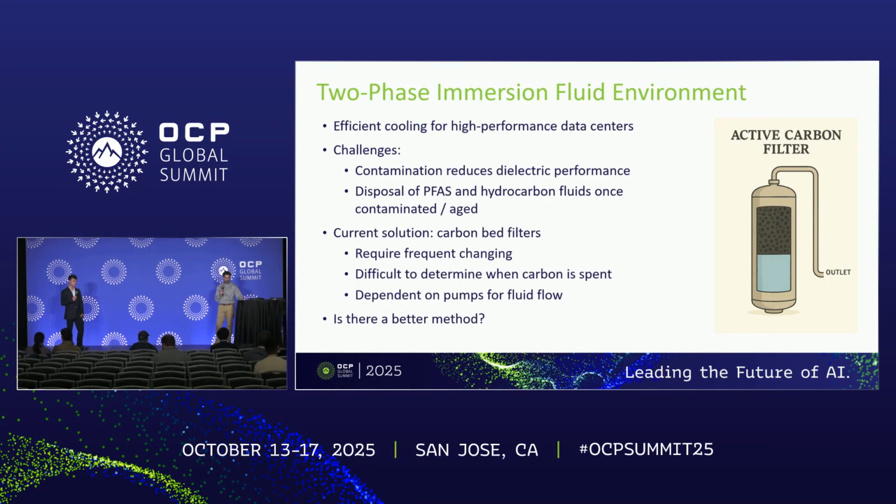The reduction in fluid performance, the means of combating this contamination is with constant filtration with activated carbon. And these carbon filters are designed to absorb organic contaminants like flux residues, oils, and plasticizers, like the ones that we identified in the FTIR analysis.